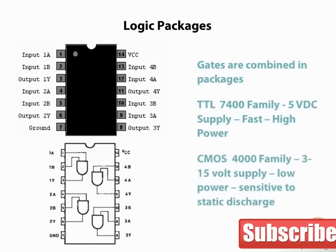CMOS stands for complementary MOS and is growing in popularity. CMOS once had the disadvantage of being slower than TTL, but now we have high-speed CMOS which rivals TTL for speed. CMOS also consumes much less power than TTL and can operate on a wider spectrum of supply voltages, typically 3 to 15 volts. CMOS does have one drawback, in that it is vulnerable to being damaged by electrostatic discharge. Circuits using CMOS need to take this into account. Good ESD practices when handling chips are necessary. The main family name for CMOS is the 4000 series. The quad 2-input AND gate to the left is a 4081 package in CMOS.